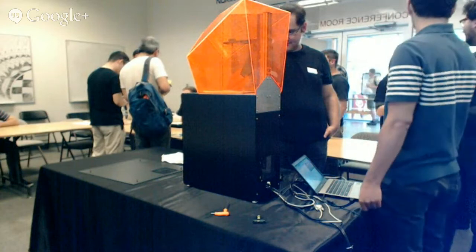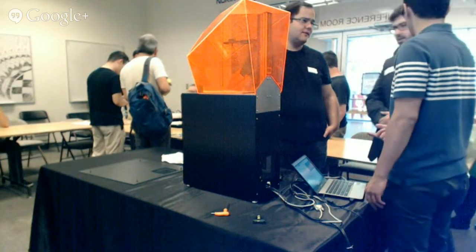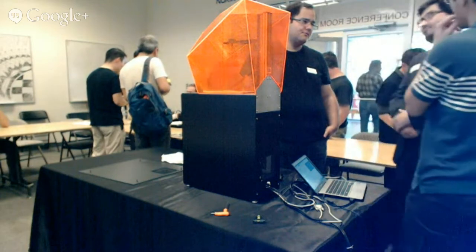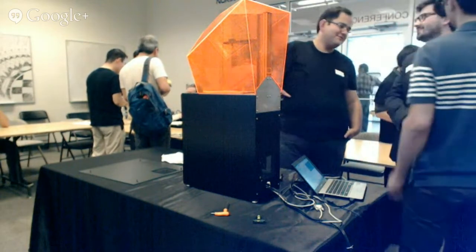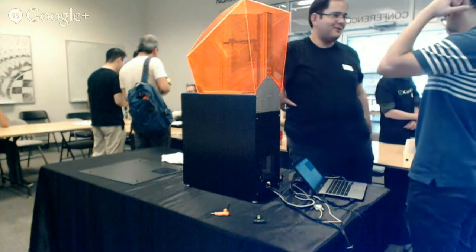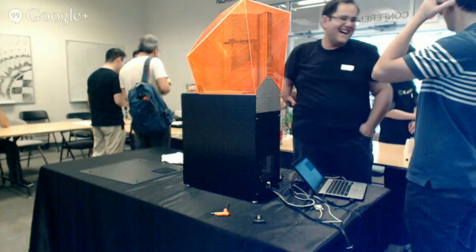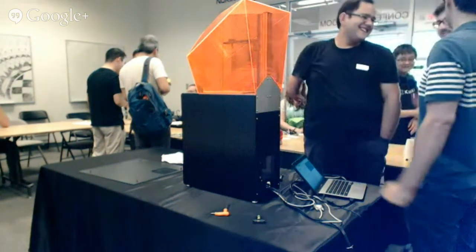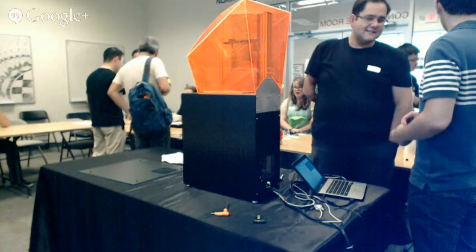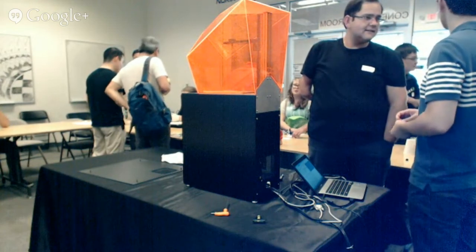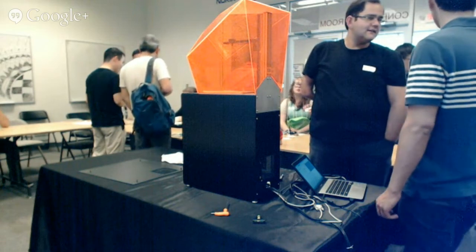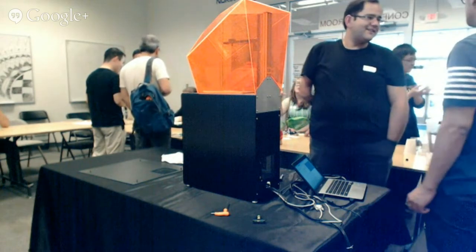It'll create distortions. So say I want something that has several parts that need to be matched to each other. That's extremely hard, because they'll shrink differently, right? You have to do a test run, determine the shrink, alter your part to take that into account. If you need to have fitting posts, right?